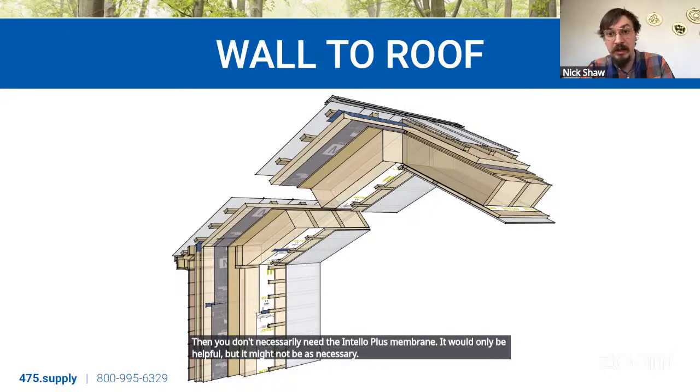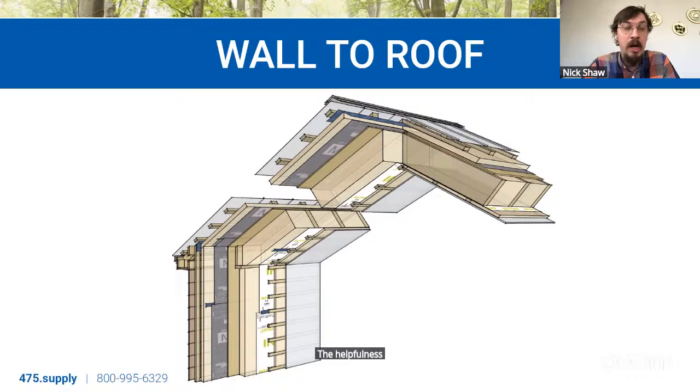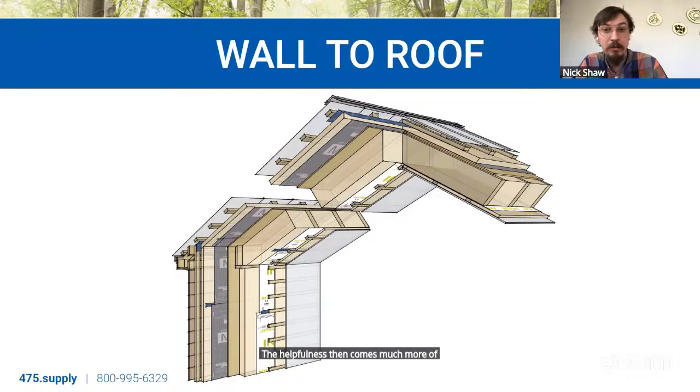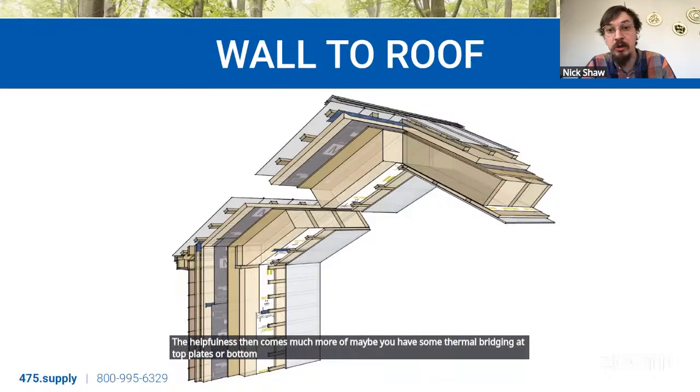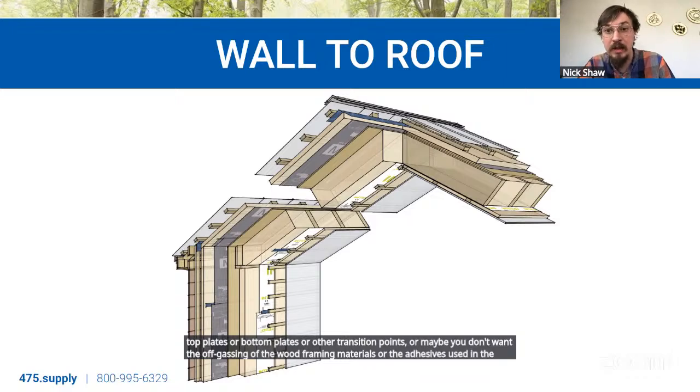The helpfulness then comes much more from maybe you have some thermal bridging at top plates or bottom plates or other transition points, or maybe you don't want the off-gassing of the wood framing materials or the adhesives used in the OSB or plywood, things like that.